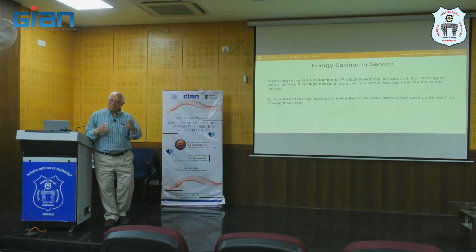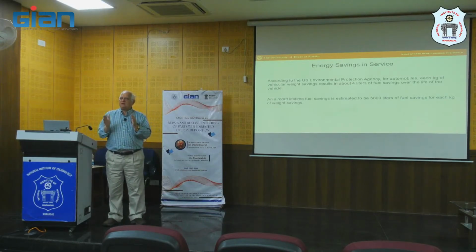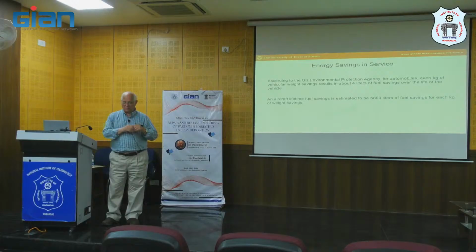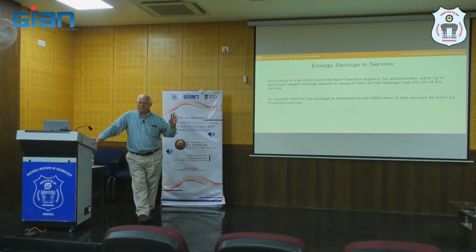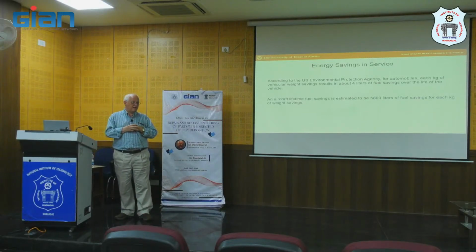And so the advantage to additive is that we can create lightweighted parts perhaps much more easily than by traditional manufacturing methods, by using cellular or lattice structures and topology optimization, and we can carry that over and enjoy the benefits in service life. So we have really these 3 areas. Actually, the 4th area I didn't really talk about very much: that's the recycling of the material. So those are the 4 areas that we look at when we do total life cycle analysis.